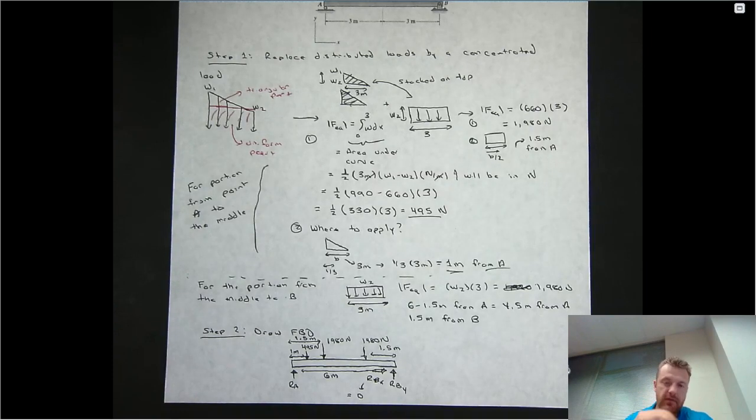In general, you can sum all forces in the horizontal and vertical direction, and you can compute a moment about 1 point. However, as I mentioned in that lecture video that I recorded, those are not unique. Those aren't the only equations you can take. You can also take 3 rotational-based equilibrium equations. So I could sum moments about 3 points.